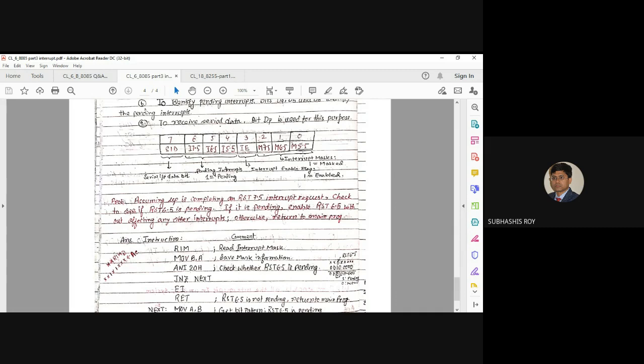If you get a non-zero value, that is 1, after the AND operation, then you understand that the value of this particular pin is 1. That is the way you get the status of a particular bit after reading. Only the RIM instruction will just read and get the data into the accumulator. Then you have to use the AND operation to understand the status of any particular pin.